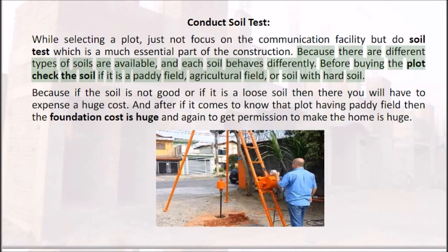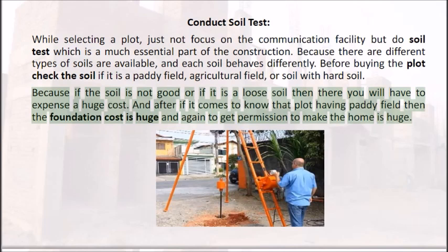Before buying the plot, check the soil, whether it is a paddy field, agricultural field, or hard soil. Because if the soil is not good or if it is loose soil, then you will have to expend a huge cost. And if it comes to be known that the plot is a paddy field, then the foundation cost is huge, and again getting permission to make the home is difficult.